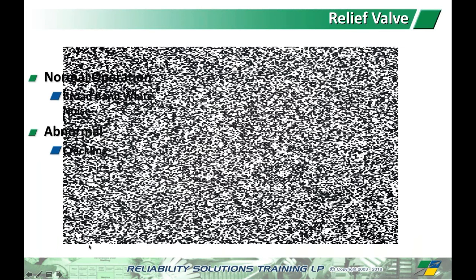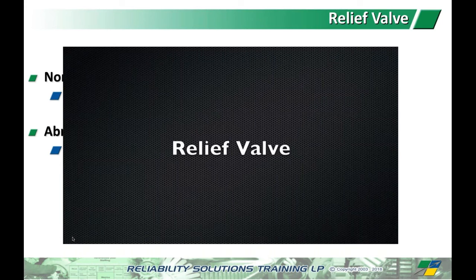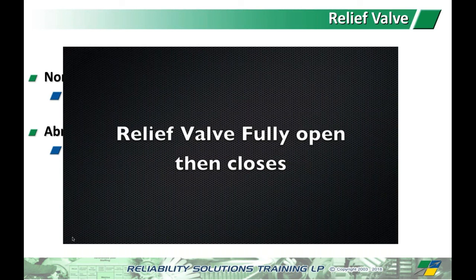A relief valve, again, knowing what normal operation is and what abnormal is important here. So let's have a listen to that. Starting to open now. Wide open and then fully closes. Now let's listen to it again.